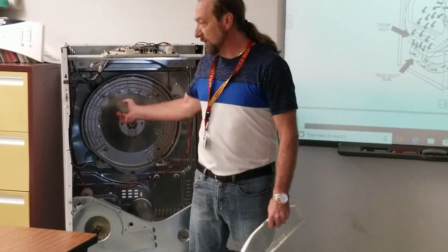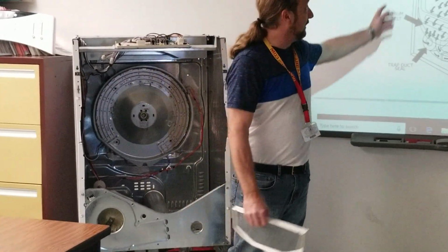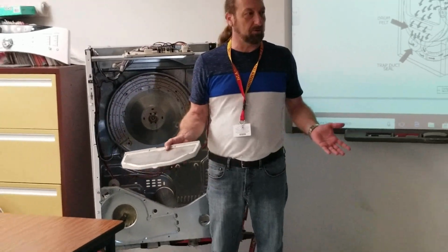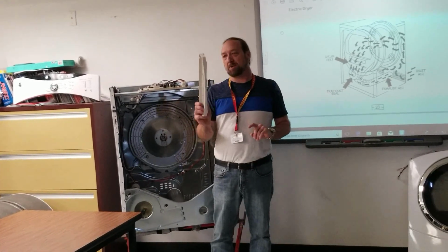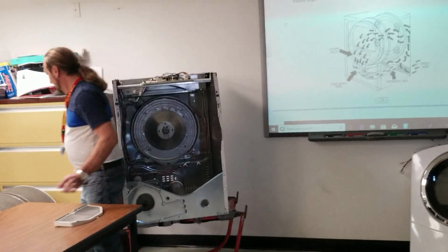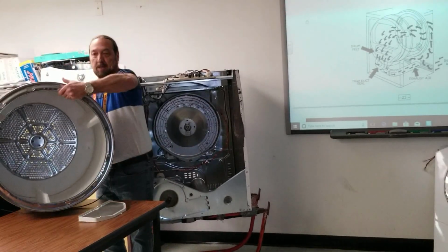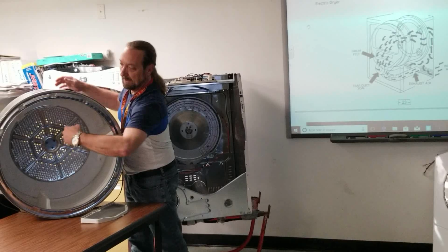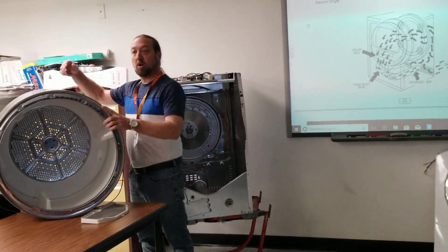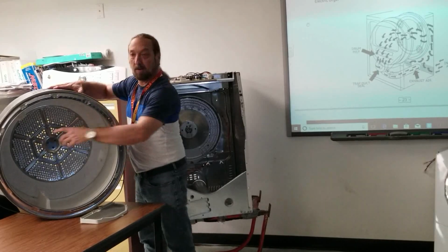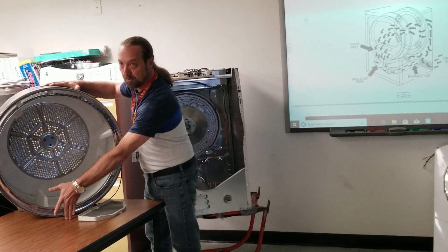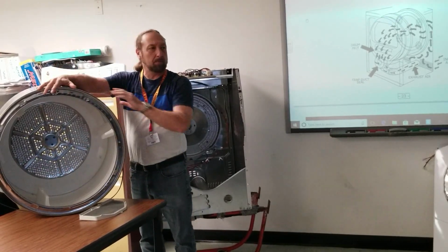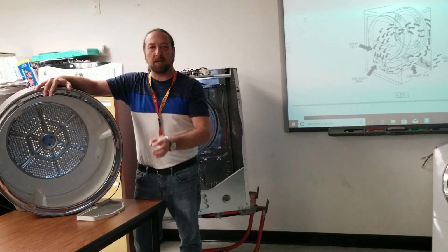There are seals around the front and the back of these drums. If the seal's bad, will the dryer dry as well as it's supposed to? No. Why not? It's not going to hold compression. Well, let me ask you a question. Here's the drum, right? We've got holes in the back and this big opening in the front. The air comes through the heating element in the back, comes into the drum, and as the clothes are tumbling, the air's flowing through it and goes down the filter in the front. Is the drum positive or negative airflow?